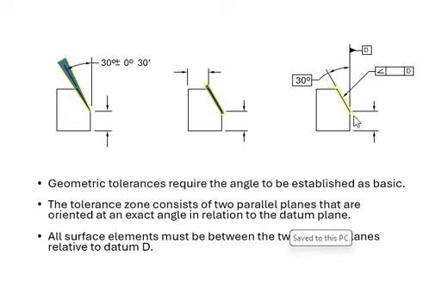Okay, now we're going to put the symbol for your datum reference. We're going to stick this datum reference symbol right here on this imaginary line, which is the extension of this surface, where we want this inclined surface and to measure the angle of that, because this is our target tolerance right there, which is the angle tolerance, because we're in an angularity geometric characteristic. So we're going to orient with this datum plane right there the exact angle right here. That's just a parallel zone right there.